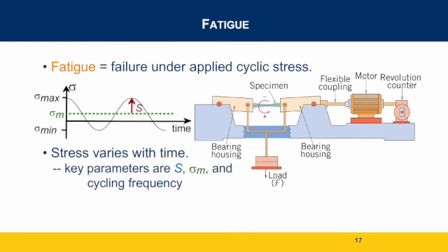All right, so let's talk about fatigue. Fatigue is a cyclical stress that's applied to a material, where you add a stress, release a lot of that stress, add it again, and release it over and over again. You do that over a cyclical time period, basically a sinusoidal wave with a maximum stress and a minimum stress, applied over and over throughout the specimen's lifetime.